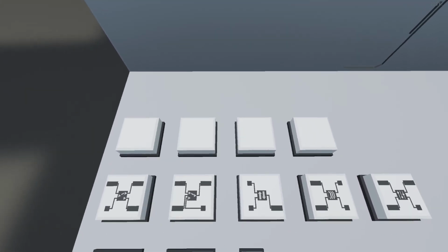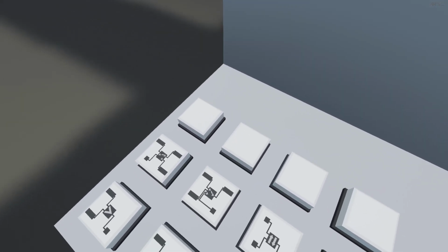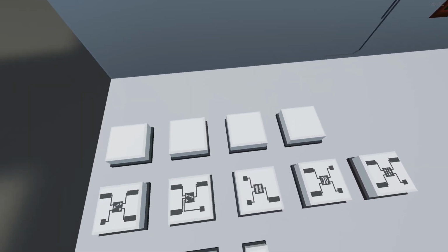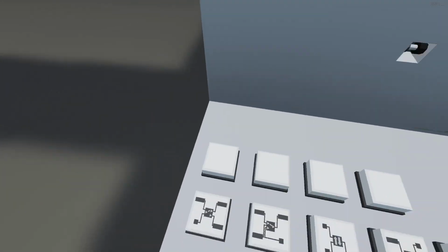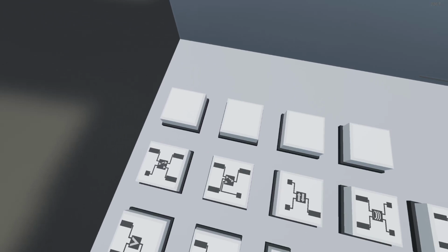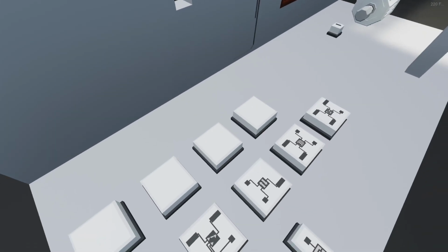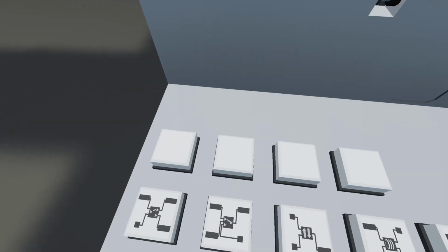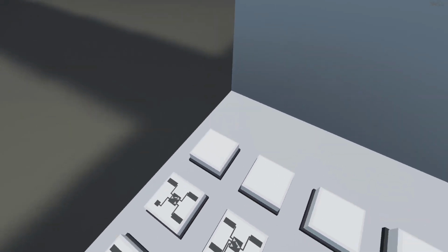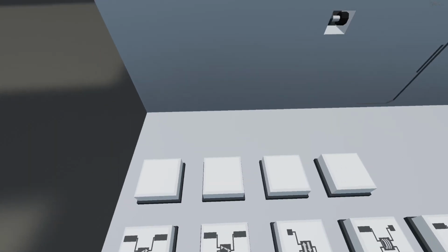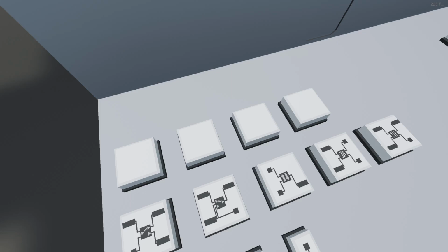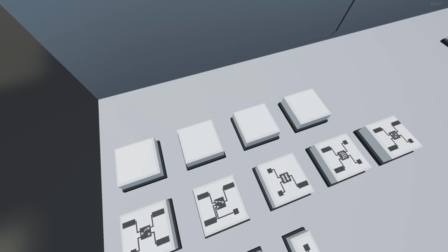And finally, on the last row, we have the timers. We have the RTF, the RTO, the TOF, and the TON. The first two have a manual reset. The last automatically reset after the timer enables are released or turned off, so to speak. And the first and the third one will put out an on signal while the duration is going down and shut off afterwards. And the other two will put out an on value after the timer duration has gone through.